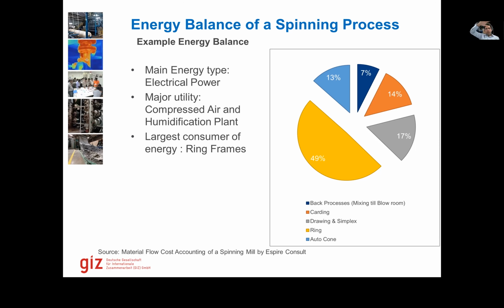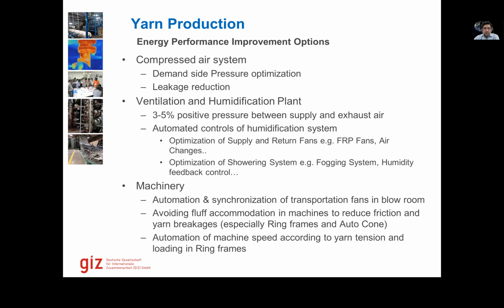From the top, we provide more air, and from the bottom, we do an exhaust. The air from the top presses the suspended particles downwards towards the exhaust, which is from the floor. The whole air carrying the fluff goes through the exhaust, then into the filters, so that all this fluff and dust is collected inside the filters, and the clean air is then exhausted.